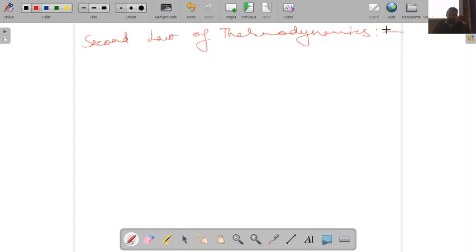So whenever we study the second law of thermodynamics, you will find that its two important statements are particularly for heat engines and refrigerating systems, which are known as the Kelvin-Planck statement and the Clausius statement. Over here in this subject we will not be dealing with heat engines and refrigerating units. Obviously we may deal with some components of, say, gas turbines, which is also a heat engine, but at component level we will not be dealing with a thermodynamic cycle. Okay, so we are not concerned about these two statements, but the second law of thermodynamics gives one important property.